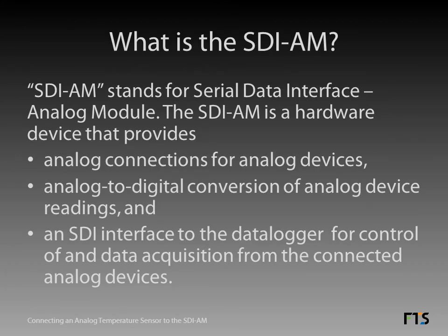SDI-AM stands for Serial Data Interface Analog Module. The SDI-AM is a hardware device that provides the following things: analog connections for analog devices, analog to digital conversion of analog device readings, and an SDI interface to the data logger for control of and data acquisition from the